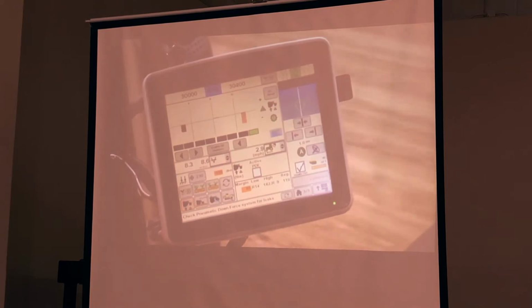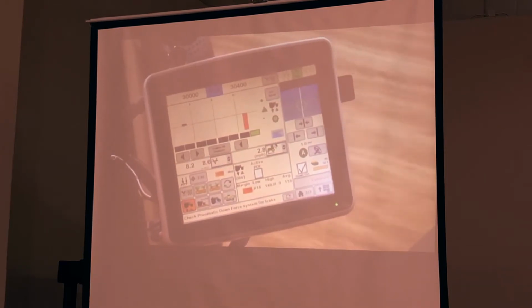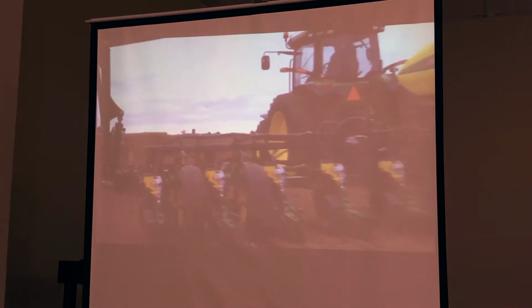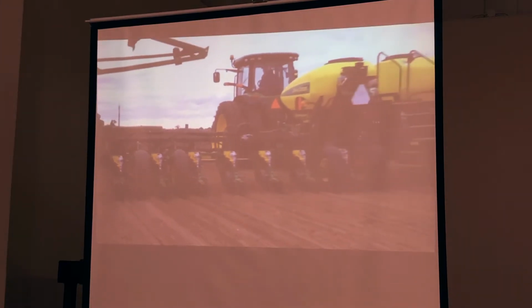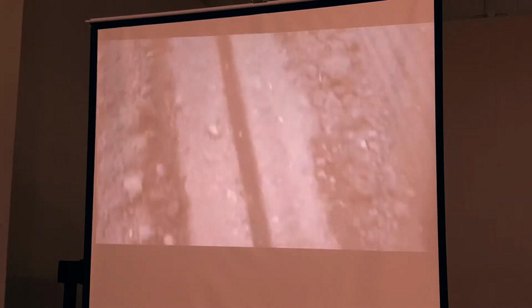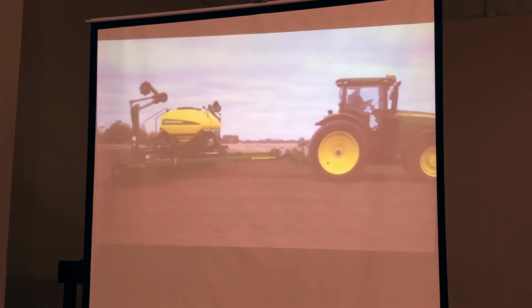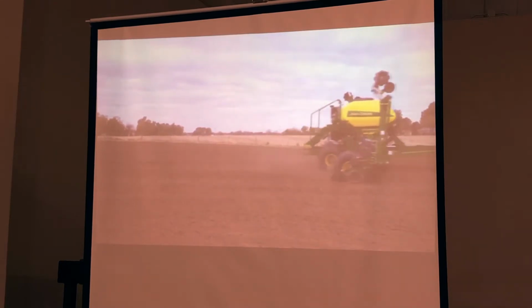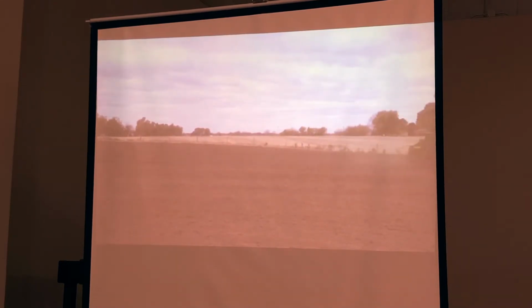The John Deere SeedStar XP monitoring system measures downforce margin with load sensors located in the row unit gauge wheel depth control handle. Setting downforce margin properly will ensure that the openers achieve full planting depth and that the gauge wheels provide enough firming of the seed furrow to prevent the walls from collapsing. Proper downforce margin also prevents excessive row unit bounce, which may cause uneven seed spacing.